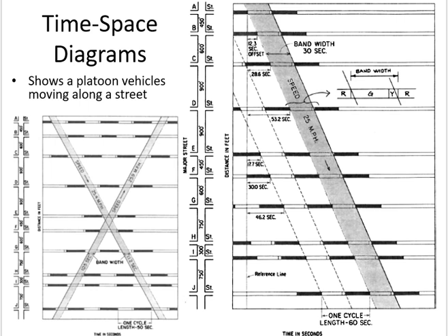So you don't have to calculate the time for the entire timeline. You just calculate the first green. After the first green, the timing is fixed. Whatever you calculated right here, after first green will start here. After that, it's fixed. I don't need to calculate it. I already did it when I was designing the signal. Okay, clear?